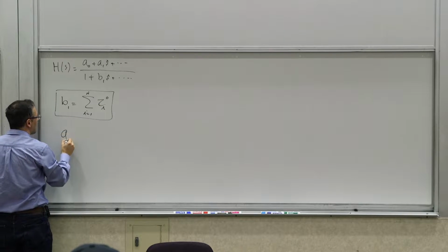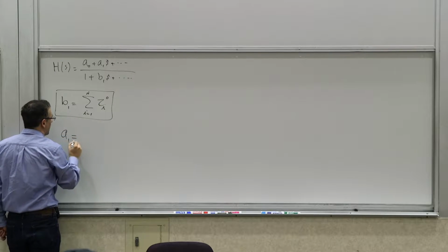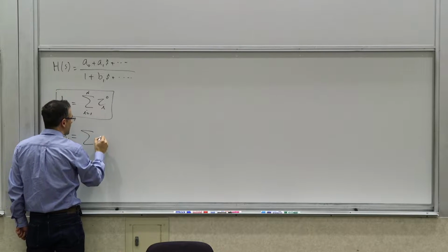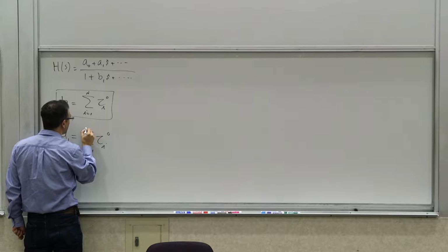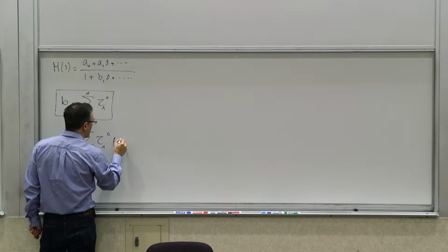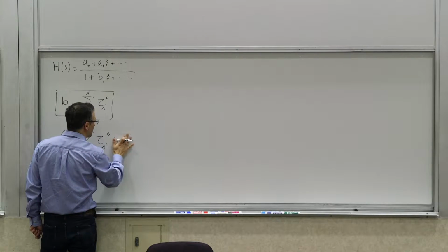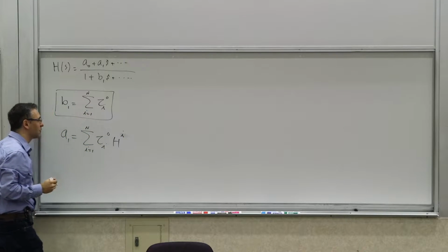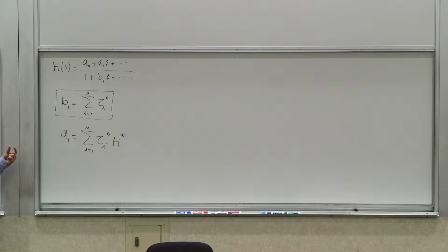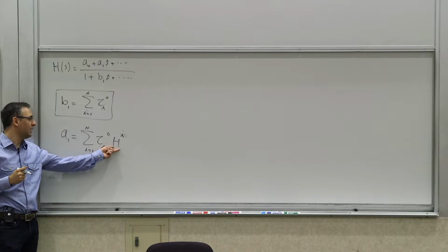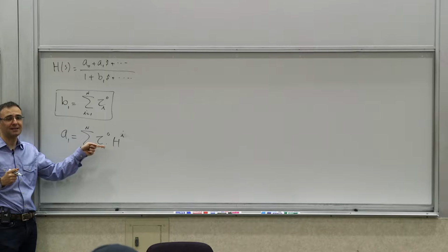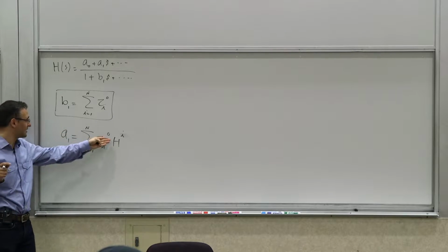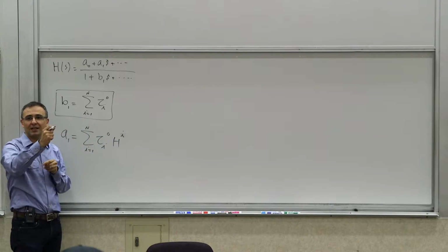And also we showed that a1 is in fact the sum of the same zero value time constants times what we call the transfer constants associated with that element. The way you calculate it, let's say it's a capacitor, you set that specific capacitor to infinite value, which means you short circuit it, and you open circuit everything else, and you see what that transfer function looks like.